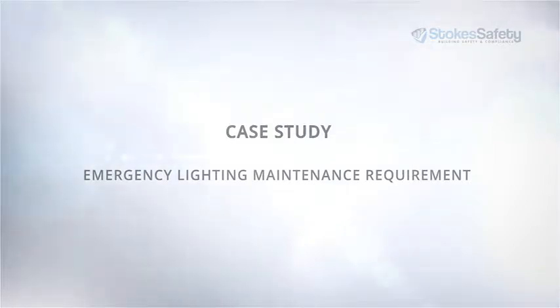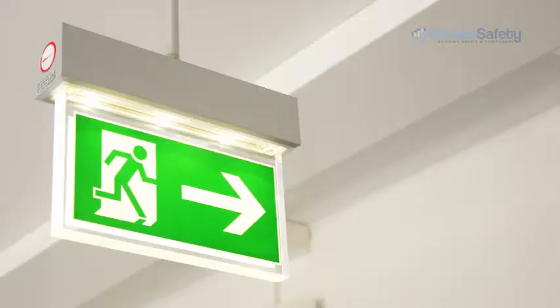So the maintenance of emergency lighting is under Australian Standard 2293. And it's listed that it's broken up into a 6-monthly test and an annual test. Basically, it's a 90-minute test. So with the emergency lighting, you basically really want to make sure that the exit lighting and emergency lighting will maintain on a battery backup for 90 minutes. So within a commercial building, basically you want to get everyone out in a few minutes, but they allow for 90 minutes or an hour and a half.